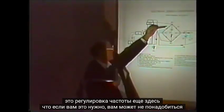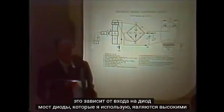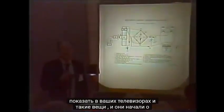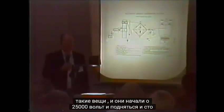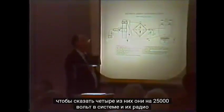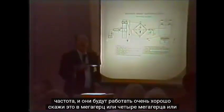Yeah, well, you've got voltage dividers. This is a frequency adjust deal here that you may or may not need. It depends on the input to the diode bridge. The diodes which I use are high voltage radio frequency diodes which show up in your television sets. They start at about 25,000 volts and go up, and 100,000 is not uncommon. So you've got, say, 4 of them there at 25,000 volts in the system, and they're radio frequency, and they'll operate very well at, say, 2 megahertz or 4 megahertz or whatever.